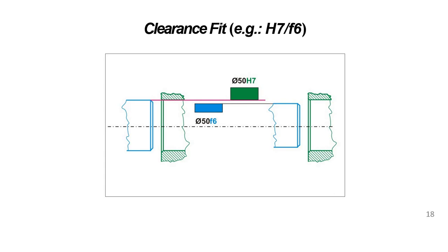Okay, always we know that there should be clearance. Clearance means the gap. If you are going to maintain a gap in a hole and shaft assembly, in that case, there should always be a shaft size that is smaller than the hole size. Okay, so the maximum size of the shaft should always be smaller than the minimum limit of the hole.